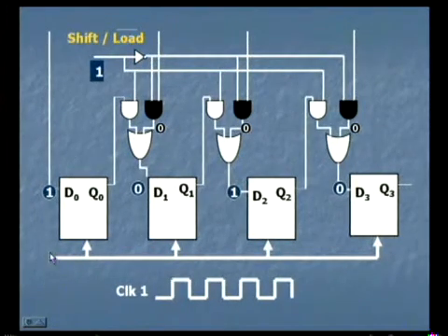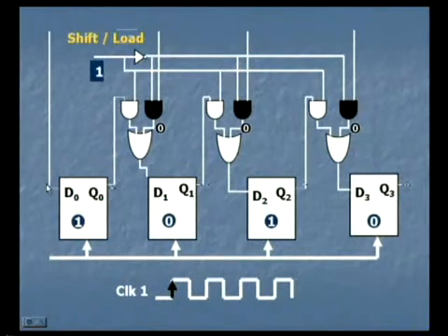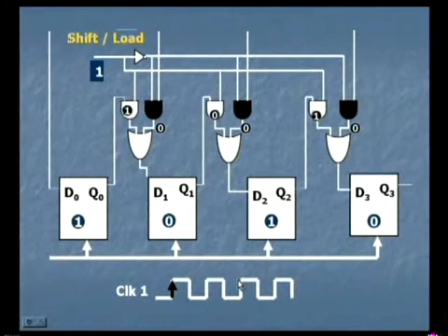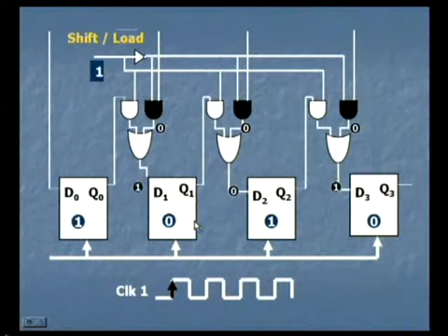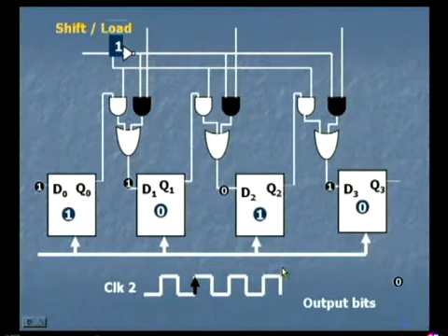See here, on the strike of the first clock pulse, this D flip flop stores the input and the same is available as the output at those individual flip flops, and that is carried on to the AND gate, and the AND gate will send the same through the individual OR gates into the next flip flops as inputs. So, at the end of the first clock pulse, the data bit 1 has moved to this place, whereas others have moved by 1 bit to the right.